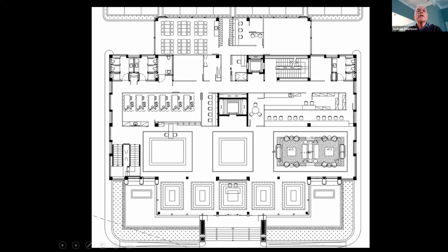in my design using Resist, I'm going to assume we've got a moment frame running along here and a moment frame running along here. You'll see that there's not a very good moment frame here because, like, see that column's quite big, and here you've got a really small column, and then you've got a larger column, large column, small column. Large, small, large. So it's not a very regular frame. And I would recommend that we would modify that to make it more regular and stronger.